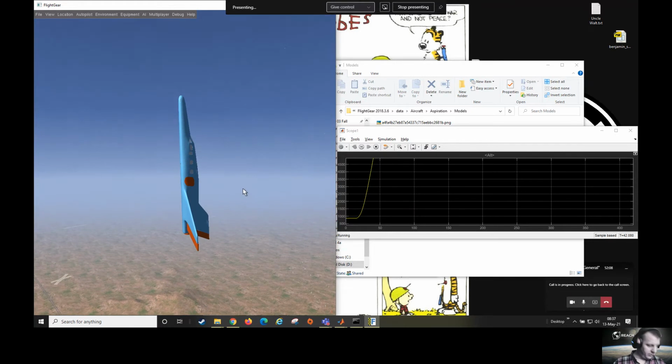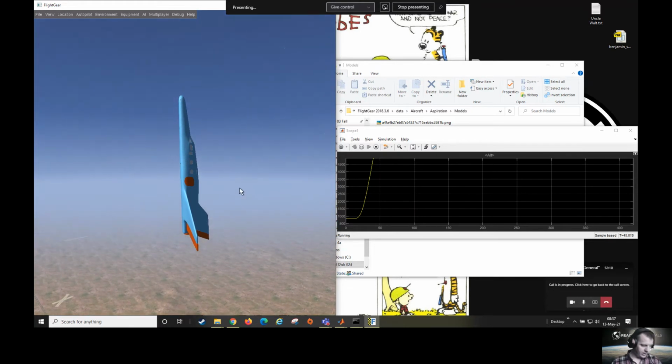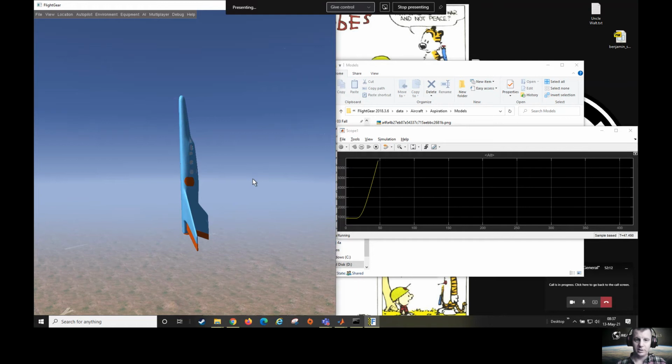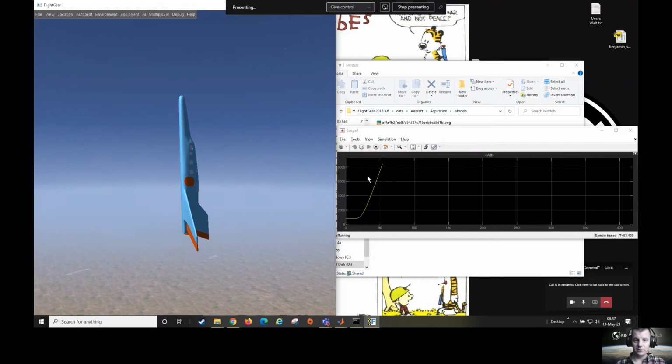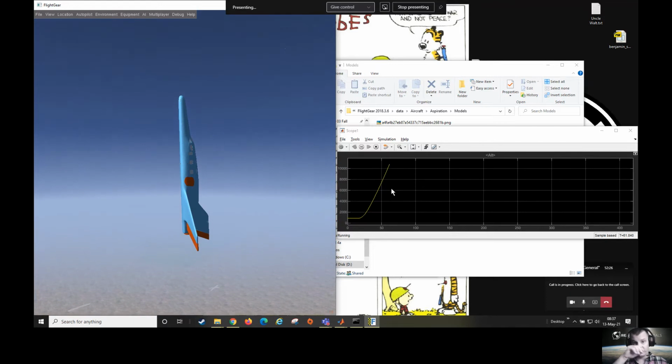So for us to make 100 kilometers, I need to generally conserve fuel initially until we get high enough elevation, 15 to 20 kilometers, and then go full throttle when density is low enough. Try and stay subsonic beforehand.